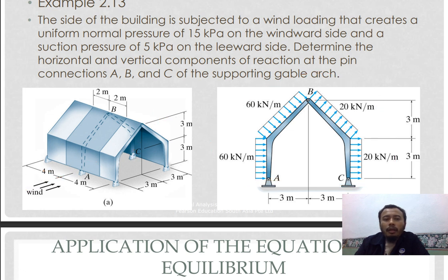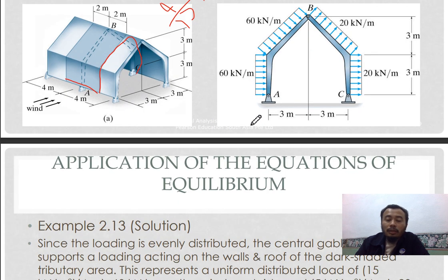You have 15 kilonewton per meter square. As we've learned before, we consider this as a one-way system. So your L2 here, and then your L1 here. Your L1 will be 4 meter divided by, I guess, around 12 meter. It's more than 2, so it's a one-way system or one-way supported slab.